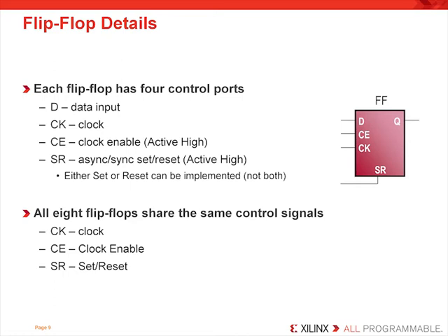This is because they cannot be implemented otherwise. Specifically, asynchronous sets resets cannot be implemented as a LUT input, but synchronous set and resets can. And we'll talk a little bit more about this implication a little later. All 8 flip-flops, now note, will share the same control signals.